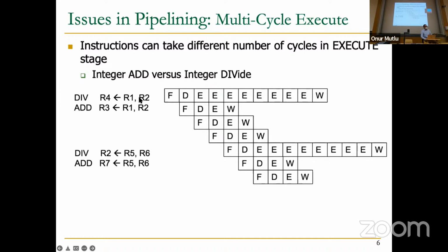The divide instruction gets fetched, gets decoded, and starts executing in this cycle. In the same cycle, the second add instruction, which is independent, gets decoded. It starts executing in the next cycle. In the next cycle, some independent instructions start executing. So let's concern ourselves with just this portion first. The divide instruction executes, and after 8 cycles, it finishes execution and writes its result back in, 1, 2, 3, 4, 5, 6, 7, 8, okay, cycle 11 over here.